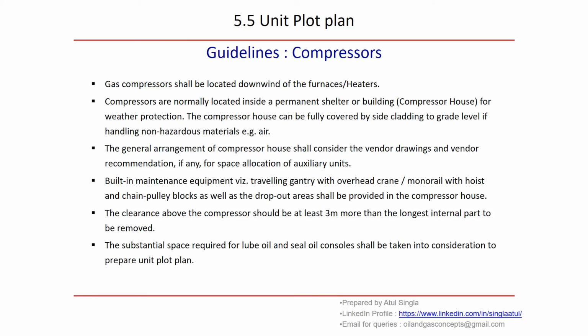The substantial space required for the lube oil and seal oil console shall be taken into consideration to prepare the unit plot plan. Once we have all this information, only then can we finalize the location of the compressor. We have to discuss all this with the vendor also. With vendor recommendation, we can finalize the location and space allocation inside the plot plan.